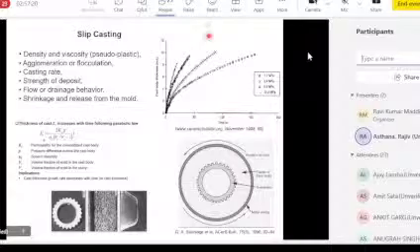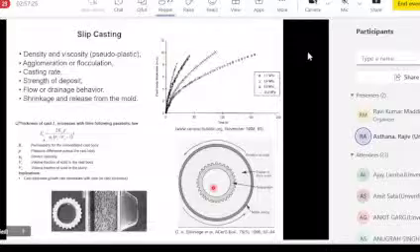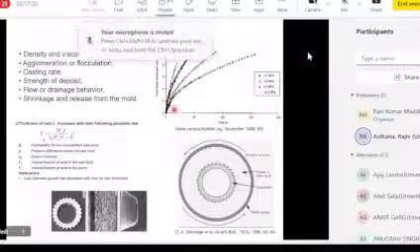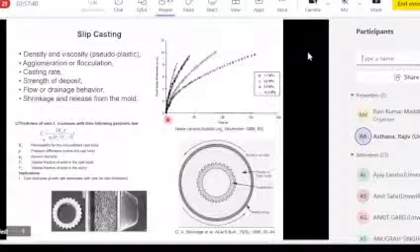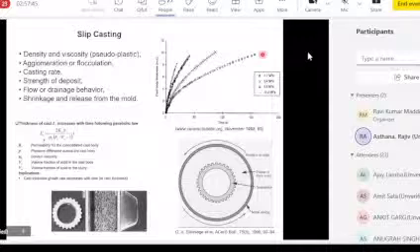But if you use the standard process without pressure or anything, then this is what the kinetics look like. The thickness of the deposit is a function of time in the plaster mold. And the graph is parabolic. Initial deposition is fast, and with time the deposition slows down just because as the deposit builds up, the liquid has to flow through a thicker deposit. So it takes more time for the liquid to be drained.